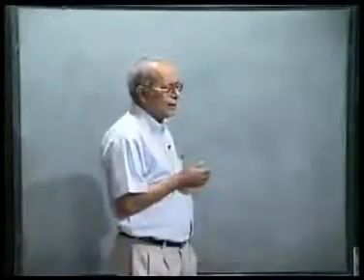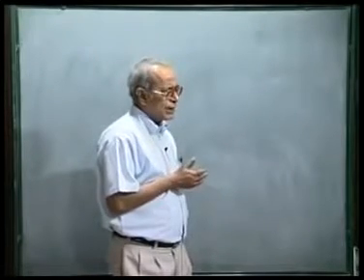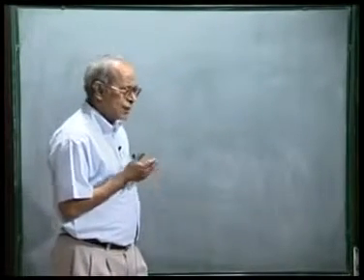Then we define different terms which will be used while designing cam follower systems, namely the base circle, prime circle, pitch curve, pressure angle, and things like that. In our next class, we shall start our discussion first with a flat face follower and show what is the need of making this offset, as we have seen in case of roller followers.